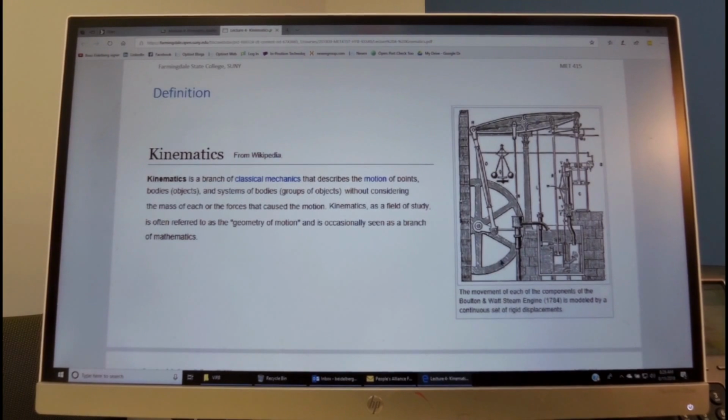The flywheel has high inertia at the periphery, therefore it could overcome the dead center on the way up. We see over here that we also have a governor. As the velocity is increasing, the governor is controlling the valves to regulate the velocity of the piston going up and down. We see over here that there's also an element that is pumping the water from an underground reservoir into the pool, and there's another valve over here that releases some of the water into the steam chamber.